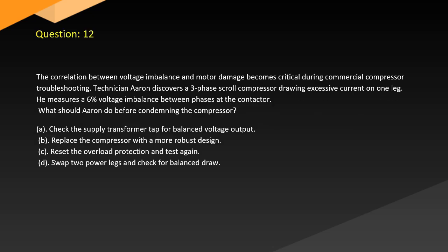Question 12. The correlation between voltage imbalance and motor damage becomes critical during commercial compressor troubleshooting. Technician Aaron discovers a three-phase scroll compressor drawing excessive current on one leg. He measures a 6% voltage imbalance between phases at the contactor. What should Aaron do before condemning the compressor?